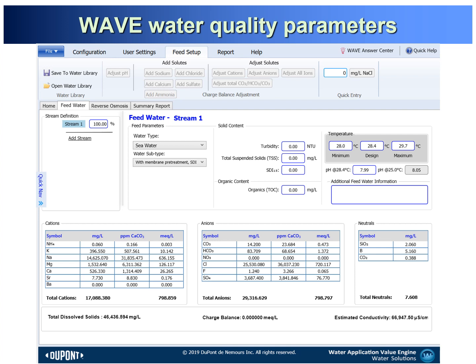So basically, the essential water parameters are water chemistry. So what's the solubility of different compounds in seawater, and what's the saturation point in terms of their inorganic scaling potential and the organic biofouling potential?